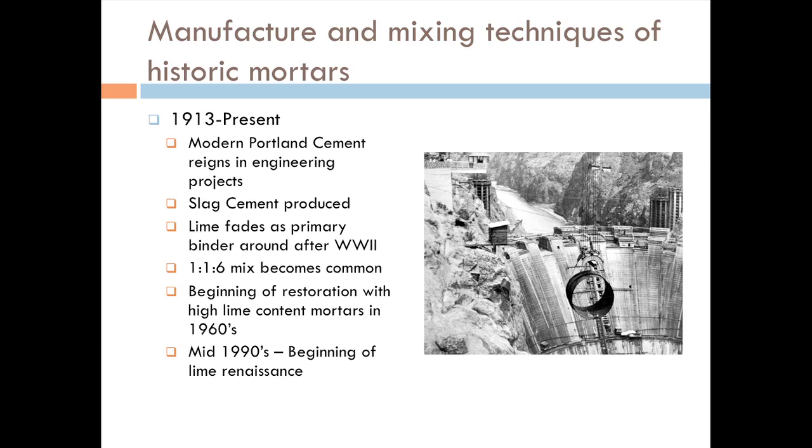But what's commonly available, which is known as Type S hydrated lime, that's used in this 1-1-6 mix, is still emitted, from what I've seen, burned at a higher temperature, just high enough to get enough out the door, but that it's not detrimental for a Portland cement blend. So if you were to take away that lime from this mix, you get something that doesn't work. Okay? If you take away the cement and use the lime that you can get today, it doesn't really work. So yeah, thank you for pointing that out. Keeping things on point.